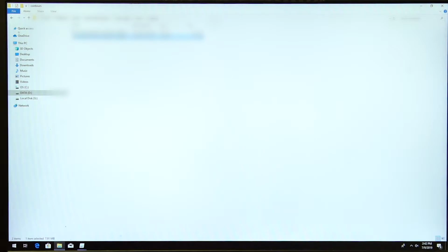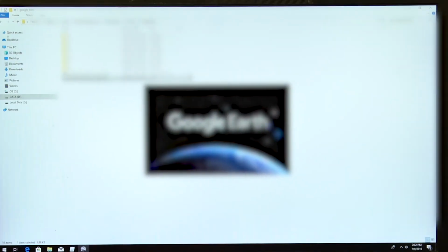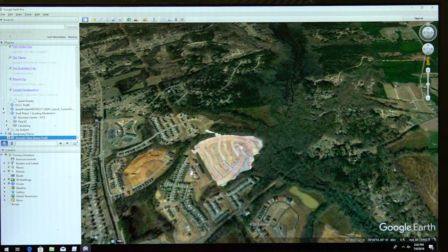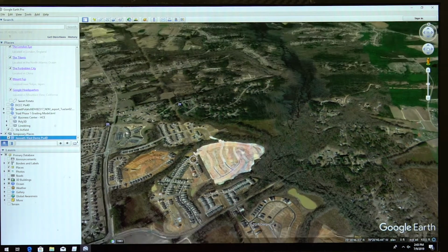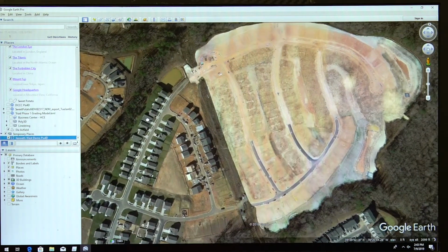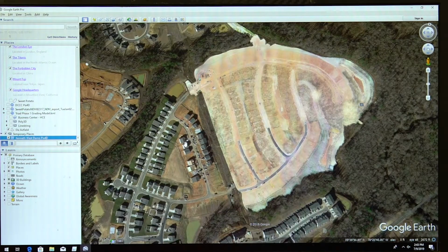Another export out of step 3 will be the Google Earth mosaic. I'll open up, you just send them this KML or double click on this KML. It opens up Google Earth. So here is that Orthomosaic that I created out of P4 tied right in to Google Earth. So this makes for a good job progression photo.